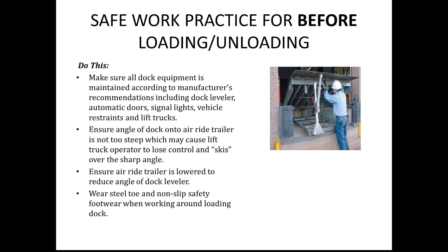The next procedure that you'd want to ensure is to make sure that the dock equipment is maintained according to the manufacturer's recommendations. So, the key thing here that you want to remember is the dock levelers are just like a forklift in terms of they need scheduled maintenance. And here you see somebody that's doing it properly with a safety device that locks out the dock plate. These are hydraulically and electrically controlled devices, and they need to be maintained on a scheduled basis.